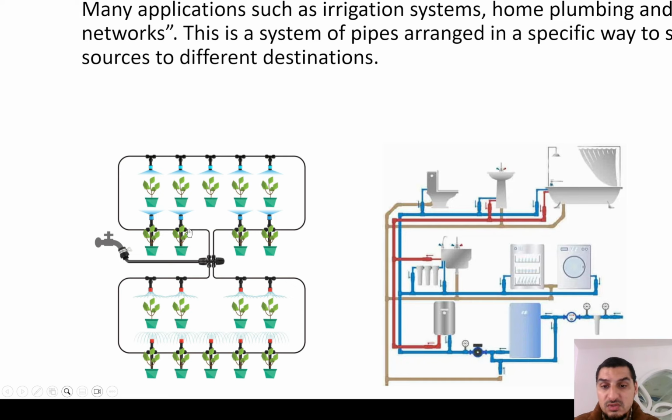And here, if they are two resistances in series, so it's like two pipes in series, they will have different resistances, either because they have different diameters, or they are made of different materials, or whatever. These are the two main things that might be the reasons. So the total pressure drop is equal to the pressure drop at 1 plus the pressure drop at 2, and the volumetric flow rate is the same for the two pipes. So these are the basics that we have.